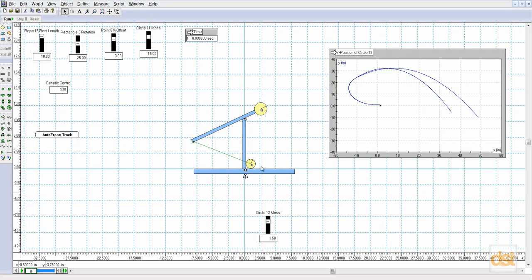Another thing we might want to do is set up a control to stop the simulation at a certain time. Really we're only interested in seeing how far the payload goes. Once it lands at y equal to 0 here, we're not interested in seeing what happens in the negative region because that's not physically possible. So we're going to define a stop control that stops the simulation when the payload crosses the 0 point back here.